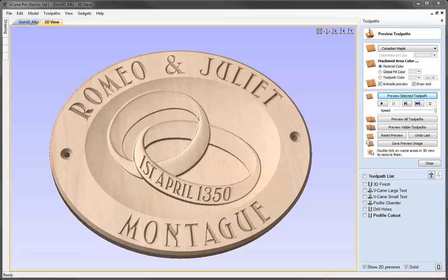And then at the end there, we looked at a nice technique for chamfering the edge of an object before finally cutting our part out and using that ability to do the last pass allowance where we cut down the edge a little bit away from the part and then step in to finish it off.